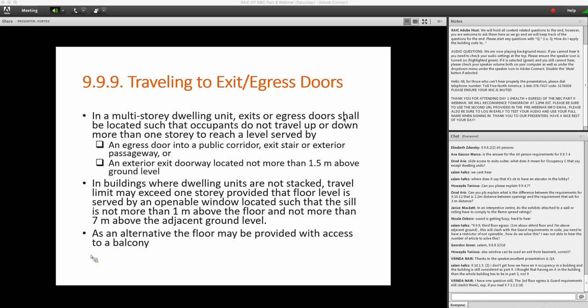And on top of that, the A2 occupancy would be the governing construction requirement. So unless you have the residential located entirely below the A2 occupancy, the A2 requirements would have to apply to the entire building. Again, I believe this will be covered in Part 3 of the webinar. Can the allowable unprotected opening under Part 3 apply to Part 9? So I do not know the context of this question, but I'll pause for a second.